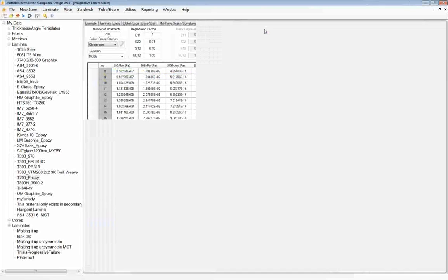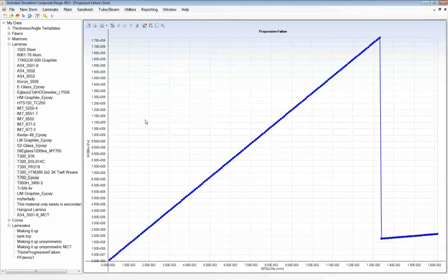And we'll go ahead and plot this again. And we're not able to quite see the stiffness reduction. Some of the materials that you'll use, you'll be able to see the softening as some of these matrix plies fail, but you'll be able to see the stiffness continue until you see your ultimate load here. And then we see this corresponds to the area where we're experiencing that massive failure of those plies. So that's one of the more common questions that we get in regards to this.